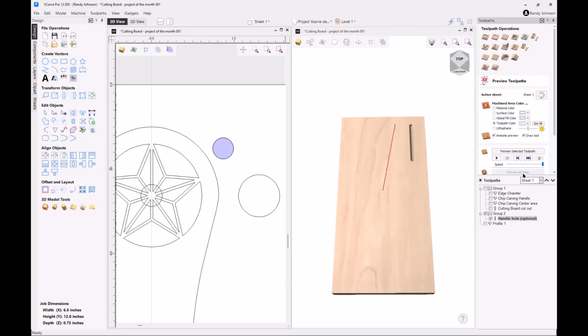So on the right side over here, something that you'll notice when sometimes you recalculate a toolpath, notice how I had this toolpath right up here with this group 1, but because I changed some of the parameters and some of the vectors, it recreated itself where it moved it down here to this other group. So just keep an eye on that. Occasionally those toolpaths will disassociate from their current location, and they will reappear down below. So if the order is important, you always want to verify that.